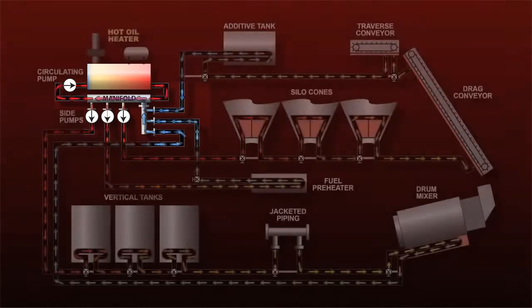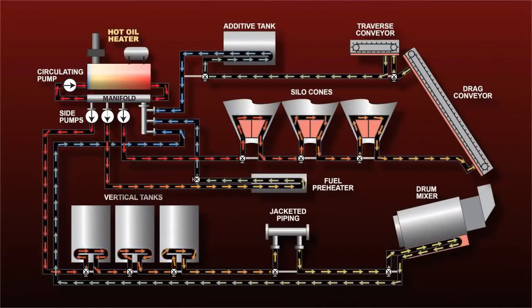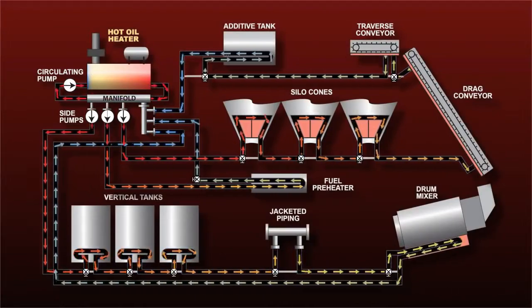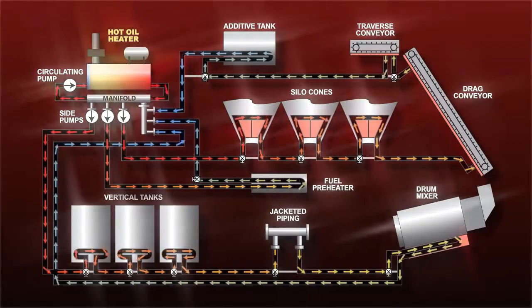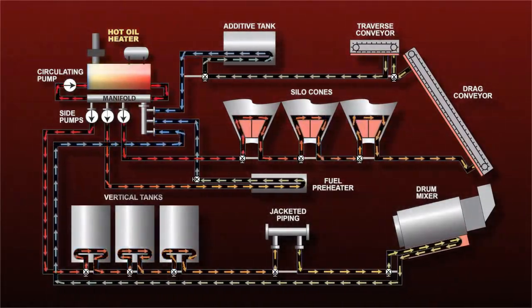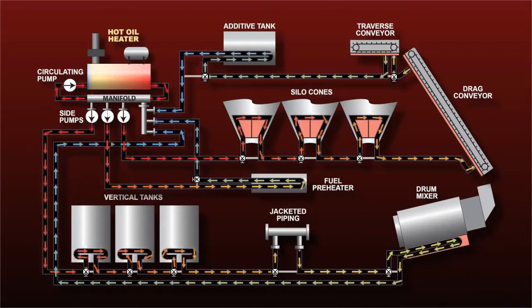There, it's mixed with the hot oil flowing out of the heater coil and cooler oil returning from other circuits. The major benefit of multiple circuits is faster oil flow to all components, noticeably reducing time to heat the components. Moreover, heater shutdowns are avoided because the circulation pump maintains optimum flow through the heater coil.